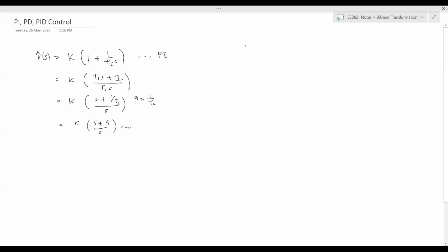So we can say G(s) is equal to K over s times (s plus 10). The closed loop transfer function is in terms of G(s). In our case, H(s) is basically 1 because there's nothing in the feedback part. It's just a unity feedback.